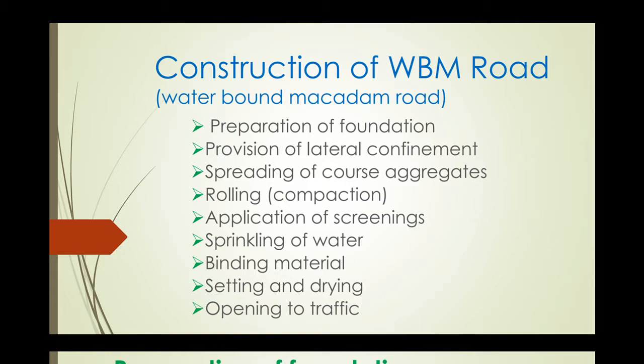Under flexible pavements, to start with we have the basic pavements for low volume roads like earthen pavements or gravel roads. Then we come to WBM roads, then bituminous concrete roads, HDBC roads. Then different types of penetration based flexible pavements. And then we have rigid pavements, which may be jointed, unjointed, reinforced or continuously reinforced. We have different types of pavements.